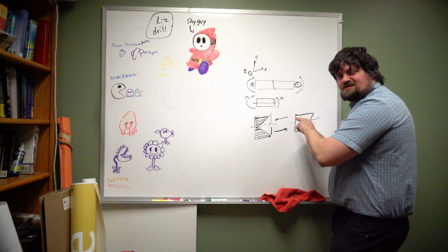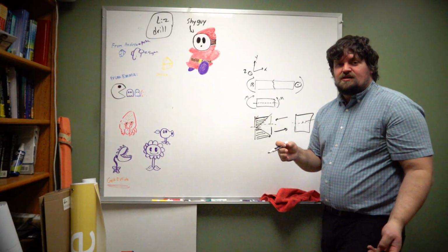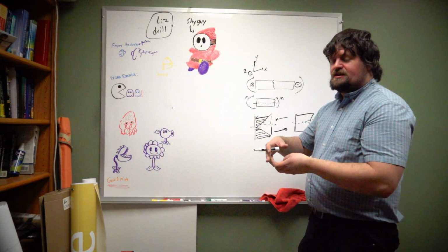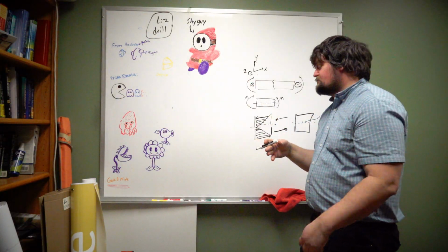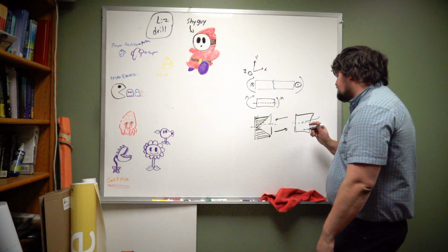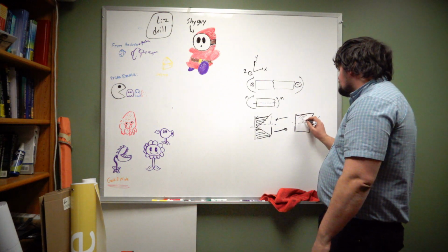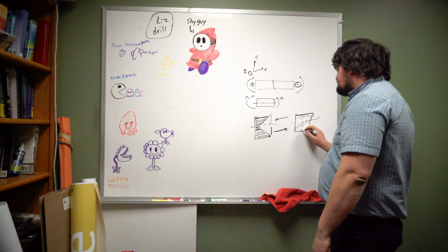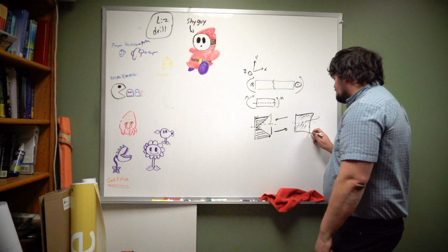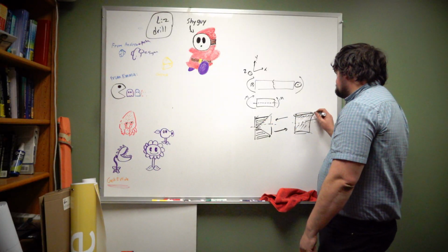This defines basically the center of the beam. Now the centroid is a geometric property based on how much material is above and below the centroid, trying to find the average center, so to speak. So in this case, this area up here will all be in compression, and this area down here will all be in tension, with the maximum tension occurring at the very bottom and the maximum compression occurring at the very top.